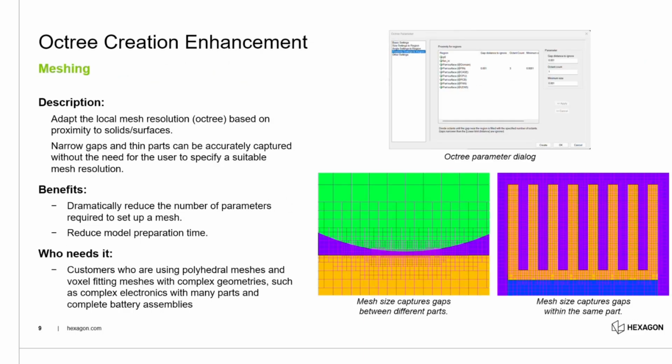If you now look at meshing specifically, the Octree, if you're not familiar with it or you haven't used it in a while, is where we specify what size the mesh is going to be once we create the mesh. The Octree is really fast to create with simply these hex-shaped elements. And if you want to mesh finer, it subdivides in two directions, subdivides again, and so on.